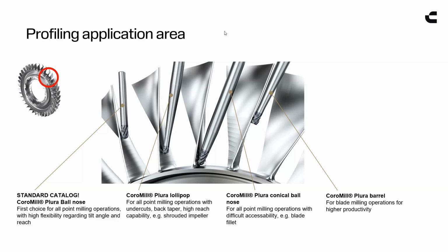So currently we have these standard Plura ball noses. They're, again, fantastic for titanium and nickel alloys. But we do offer special solutions for lollipop tools, conical ball mills, barrel tools, tangent barrel tools. So a complete, total package to machine turbomachinery.